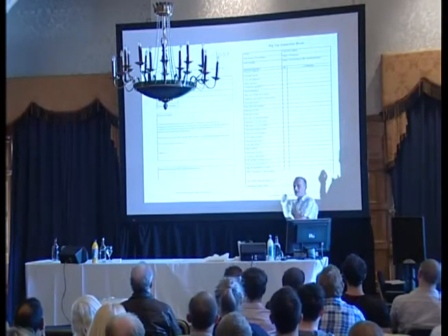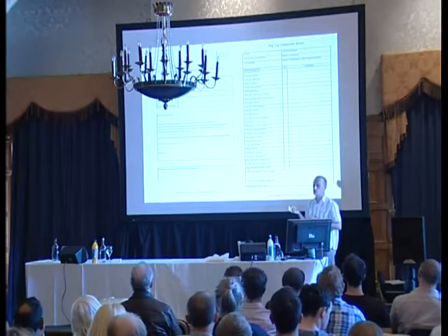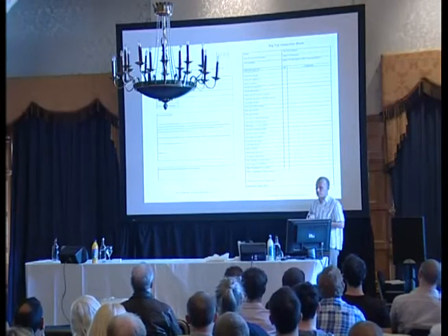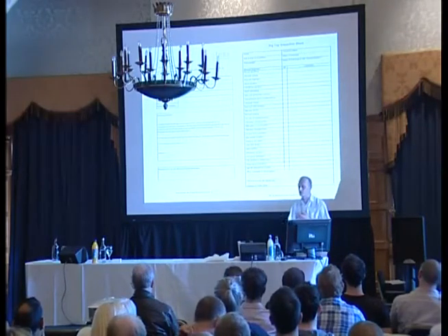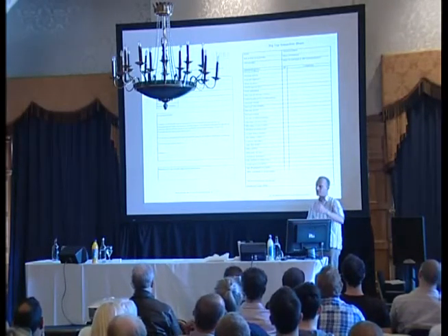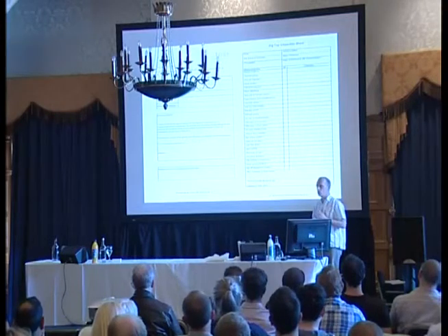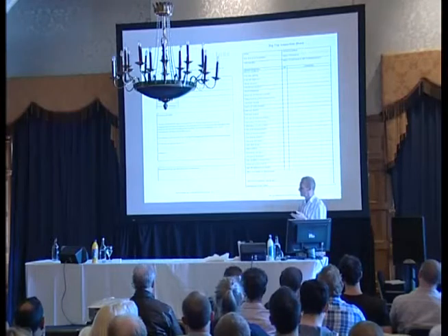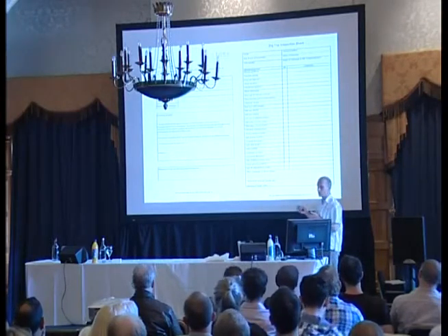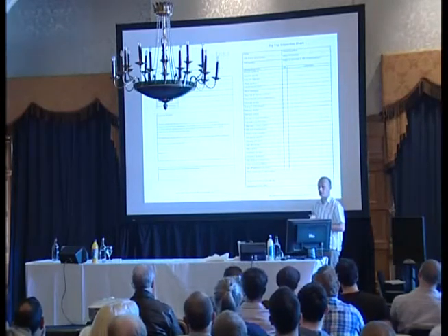All kind of things that are absolutely critical if you're building a big top. Yeah? I don't build big tops, but I get an awful lot of big tops on the sites that I'm working on, and that acts as an aide-mémoire for me. When I'm walking around with the person who's going to actually sign it off from the tent manufacturer, the tent supplier, I can go through all of those and go, has it been done?